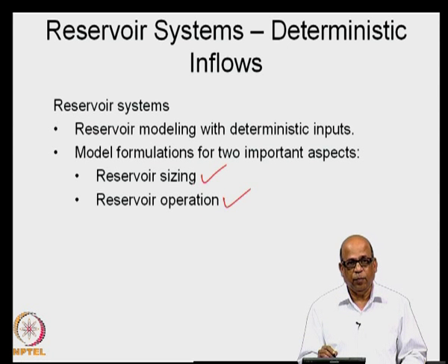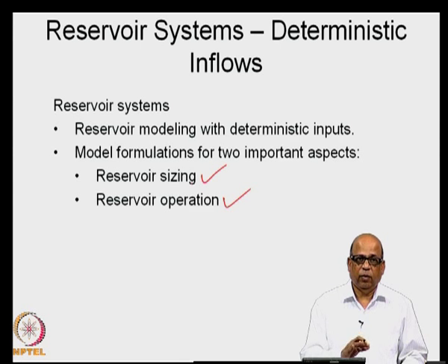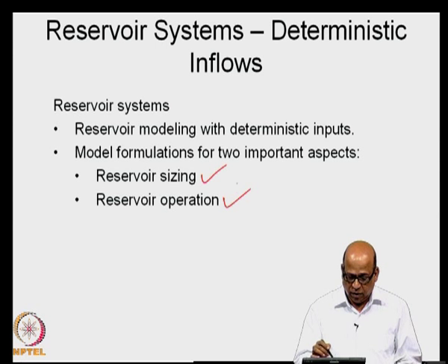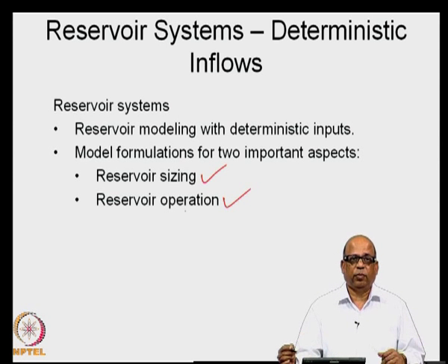The reservoir sizing problem deals with obtaining a minimum reservoir storage for a given sequence of inflows to meet a given sequence of demands. The reservoir operation problem, on the other hand, deals with the operation of the reservoir from time period to time period to meet a certain demand for a given sequence of input.